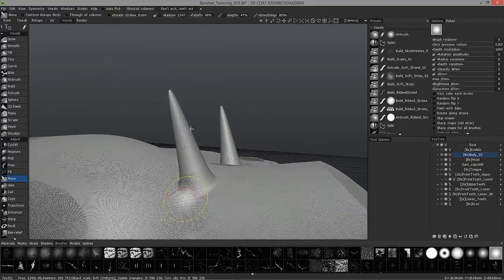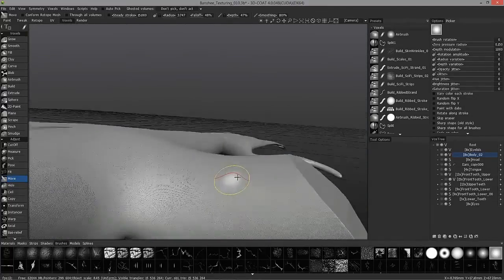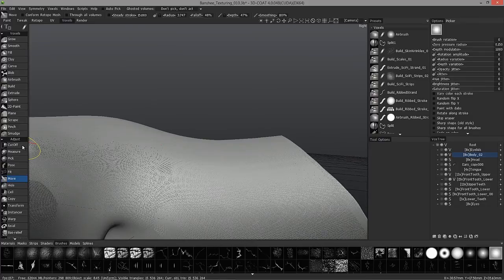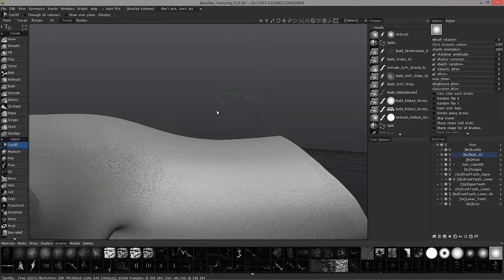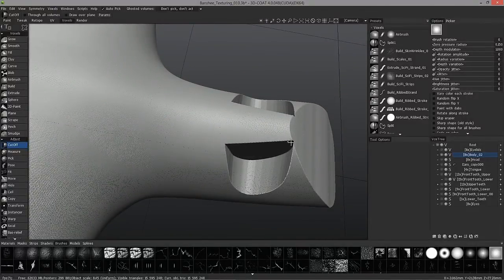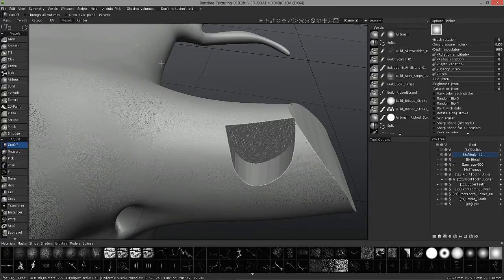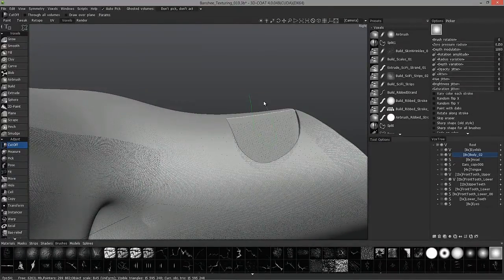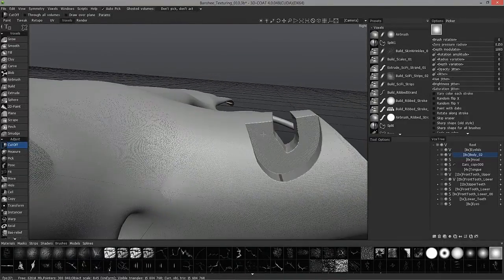Okay, and also when working with Booleans, I'm going to undo that. Okay, and when working with Booleans, let's use the Cutoff tool. Let's choose something kind of a free form. And you'll notice it only cut a portion of the way in, and that's because in the E panel the depth limit was turned on. If you uncheck that and then make a cut, it goes all the way through. And you notice how fast it did this, but if I use the Cutoff tool in surface mode,